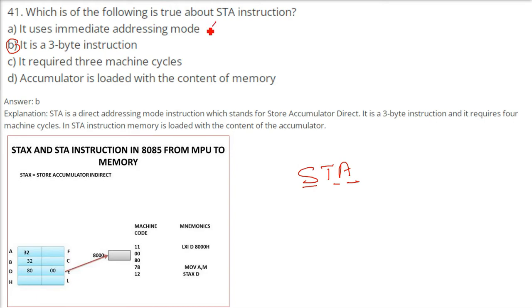It uses immediate addressing mode. No, it uses direct addressing mode, because the address is directly given after STA. 3-byte, yes. It requires 3 machine cycles. No, it uses 4 machine cycles.